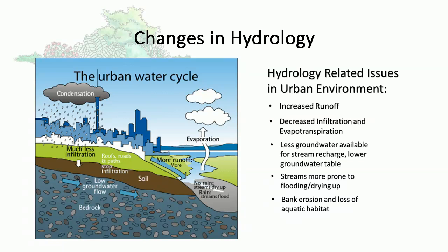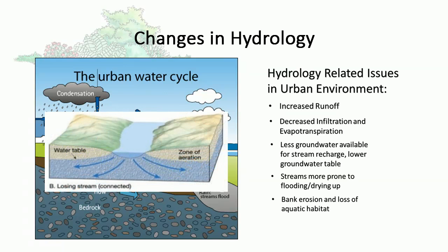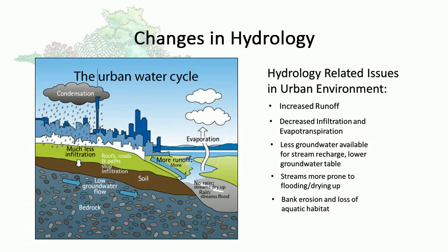Groundwater storage plays a vital role in regulating the baseline flow of water in streams. Water flows into streams from the ground when the water table is at or near the same elevation as the stream. When there is less water held underground, streams aren't able to be replenished as quickly and baseline flow levels are lowered. If there isn't much natural ground cover, as in an urban environment, groundwater isn't available for river recharge. This is magnified by spells of dry weather.